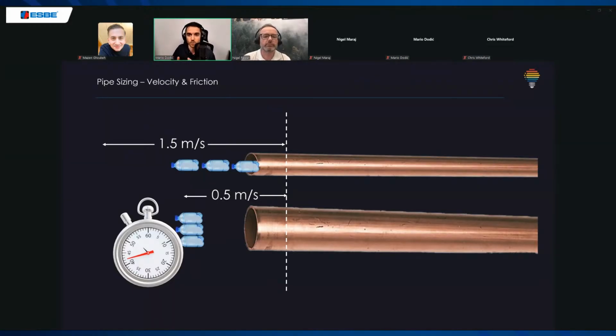Sometimes you cannot change the pipe, and it is important then to check other elements, which we will mention later on. Between these elements you can play and choose what is best for your system. Maybe one valve or one pump will make the difference for erosion, noise, and other things we don't need and want in our heating system.